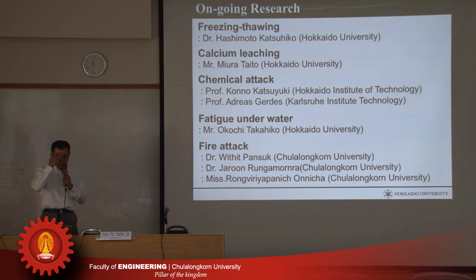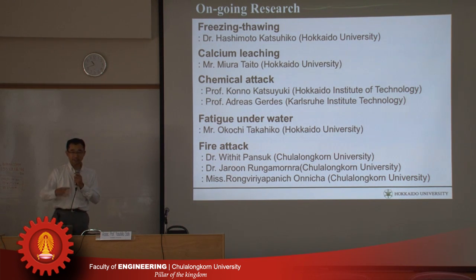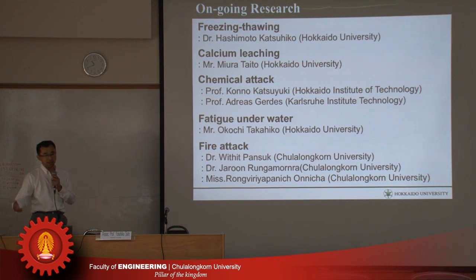In fact, we are now detecting the amount of CH and CSH after the fire attack. And in fact, last week, we got the first results. What surprised us is that after 60 minutes or 120 minutes, there was completely no CH and no CSH. And that's why we have very small strength. So anyway, this is what we are doing.